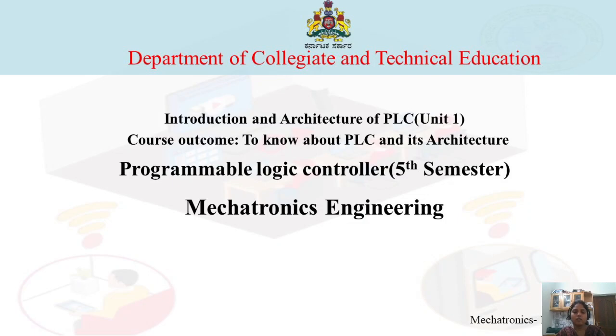Then after that, we have seen the difference between relay logic control and PLC logic control. Relay logic is nothing but a network of wiring of components. The main disadvantage in the relay logic is the elaborate wiring system. But in case of PLC, everything is done in the system. So that is why today in every industry they are preferring to go for PLCs.